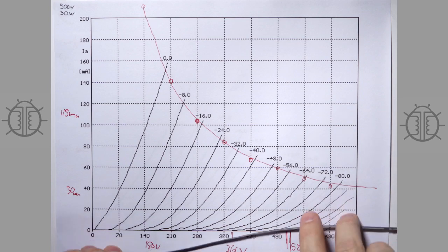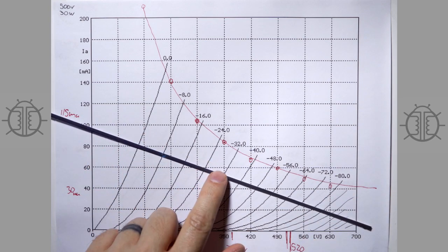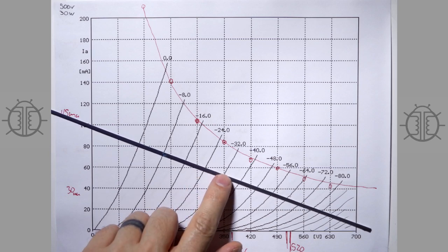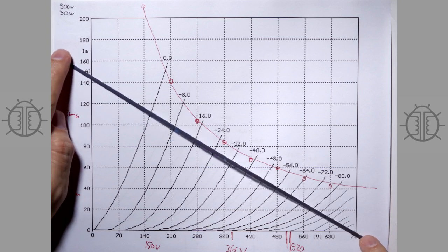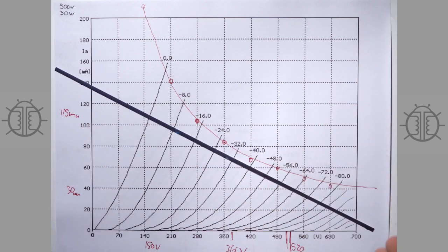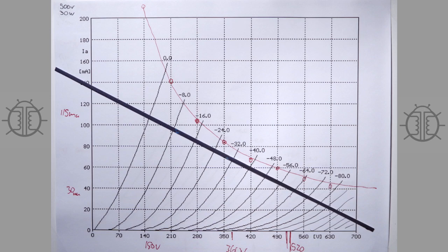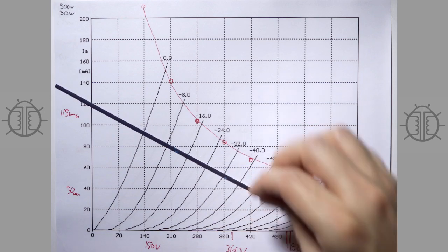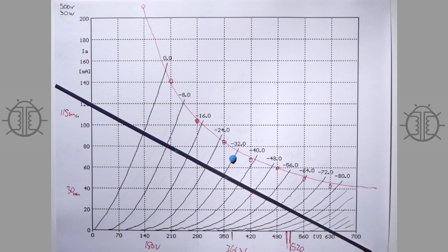Now, if you're doing a Class A push-pull stage, you haven't got to worry about that. You just take your 8K plate-to-plate or whatever it is you've decided to do, and you can discover what you want by just placing a reasonable load line here, and just sort of figuring it out. And you don't have to worry about transitioning to Class AB because if you're doing Class A, you're going to be biasing, setting your output point somewhere up in here. Now, you're going to see in a second here that Class AB operating points are very different.